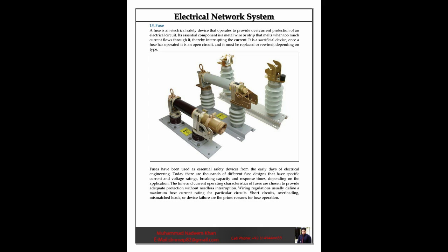13. Fuse. A fuse is an electrical safety device that operates to provide overcurrent protection of an electrical circuit. Its essential component is a metal wire or strip that melts when too much current flows through it, thereby interrupting the current. It is a sacrificial device. Once a fuse has operated, it is an open circuit, and it must be replaced or rewired, depending on type.